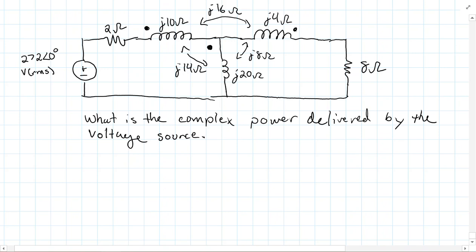Now, this problem looks confusing at first. What we've got going on here is that this really could be another transformer. It doesn't look like the transformers we looked at in previous lessons, but this sometimes happens: you'll have a single primary coil and then two secondary coils that you could attach in series, or leave and attach in parallel. This has already been configured in a particular way, but the key thing is we have magnetic coupling between three different inductors, and the magnetic coupling is different.